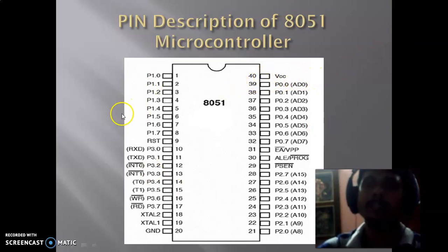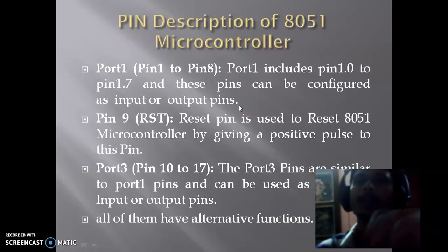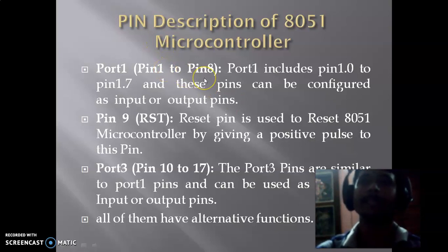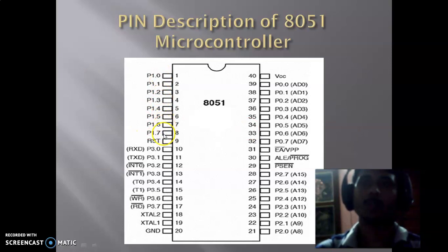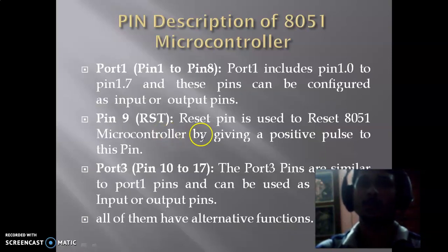So this is the pin diagram of the 8051 microcontroller, and I am going to discuss every pin of the 8051 microcontroller. First is port 1, that starts from pin 1 to pin 8. Now this port 1 includes P1.0 to P1.7, so this can be used as input as well as output.